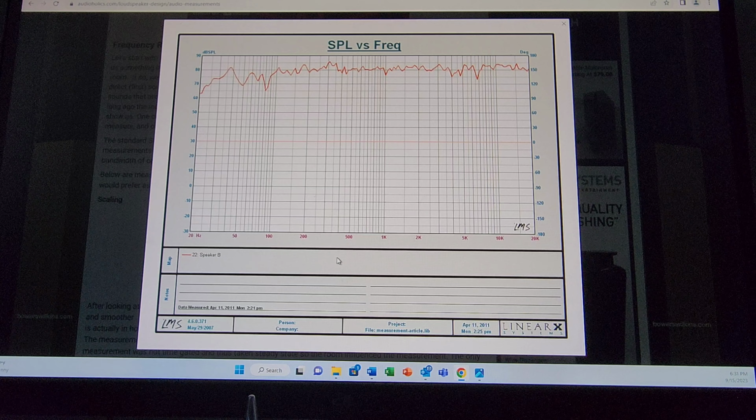The only thing that did change is we changed the shape of the diffractor over top of the speaker from the circular orb to the cone diffractor that's designed like an exponential cone. And what we found on average was over a 2 dB gain across the board on all frequencies when we put that diffractor in place.